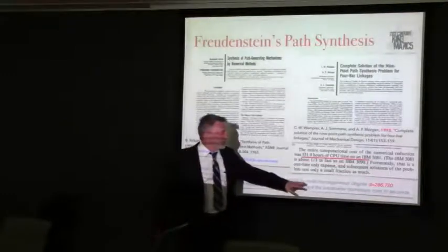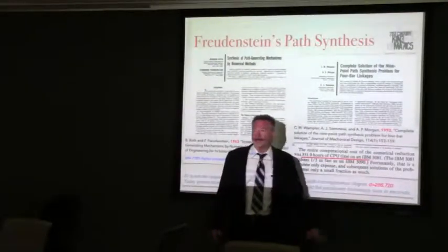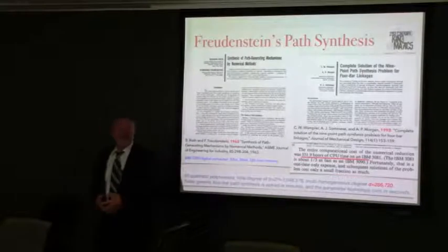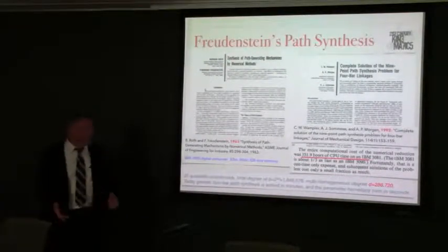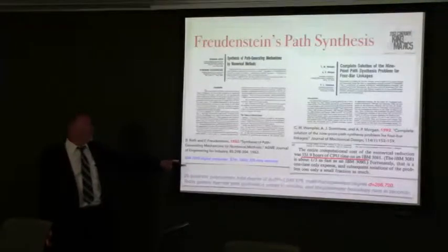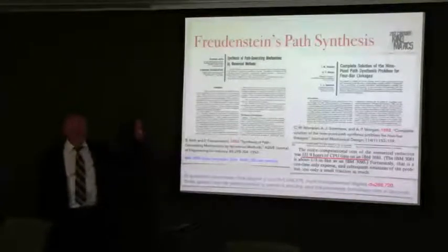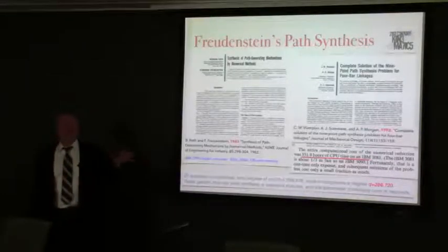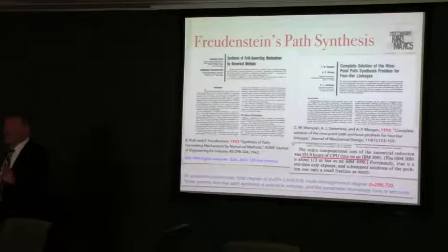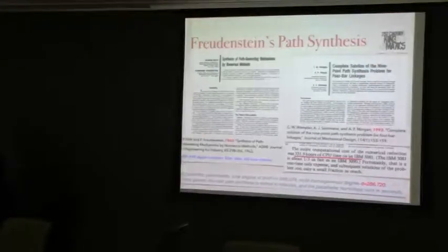But in this case, there's quite a bit less than 1 million roots. There were 200,000. So your computer has to now track all of these points. Using homotopy techniques, we can do that. It took them several weeks of calculation, but they solved it, found all of the solutions, and showed that an arbitrary 9-point path synthesis problem has 1,440 solutions.